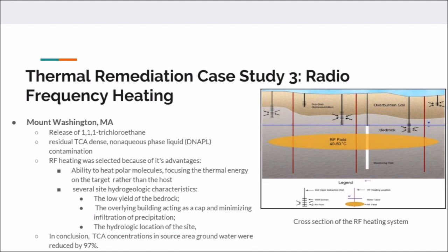system was designed, constructed, and began operation in December 2003. The treatment system included a network of 9 100-foot deep, 8-inch diameter boreholes, an RF generator, a 4-probe transmitter array, and a SVE system for control and treatment of vapors. The RF heating system consisted of a 27 megahertz, 4-channel, 20 kilowatt RF equipment trailer, transmission lines, 4 watertight antennas, applicators, and fiber optic thermometry.